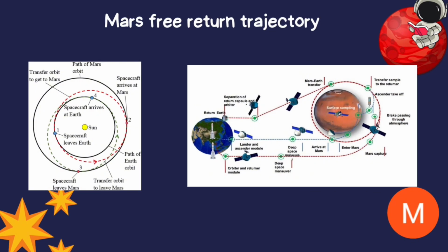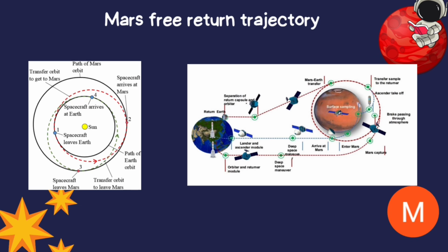After a 460-day stay on Mars, the spacecraft begins its return trip to Earth. This requires careful timing to ensure Earth and Mars are aligned, with Mars approximately 74 degrees ahead of Earth at launch. Next, the spacecraft uses another Hohmann transfer orbit for the return. On approaching Earth, it slows down using retro rockets and aerobraking through Earth's atmosphere to safely re-enter.